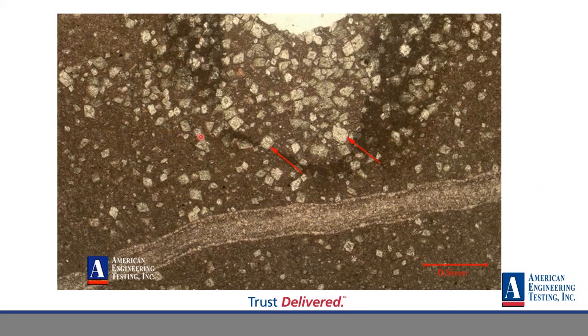I did see a presentation done by the U.S. Army Corps of Engineers about a year ago, and they said that they had a dam that experienced alkali-carbonate reactivity issues, and it caused their dam to expand a foot or two or something like that. So they had to saw cut joints to relieve pressures.